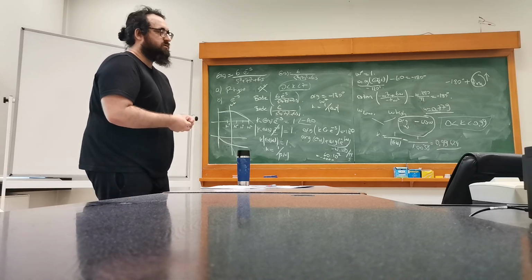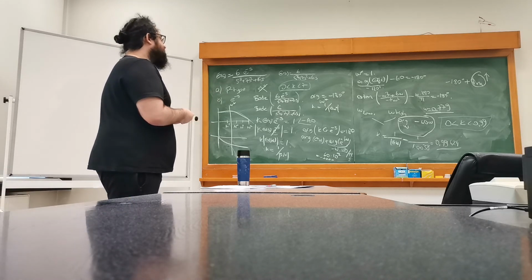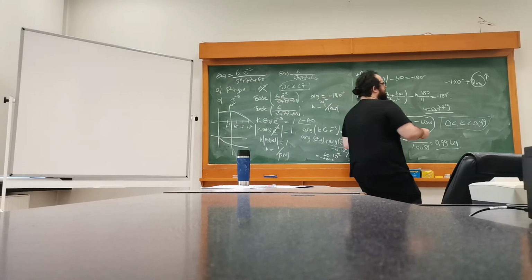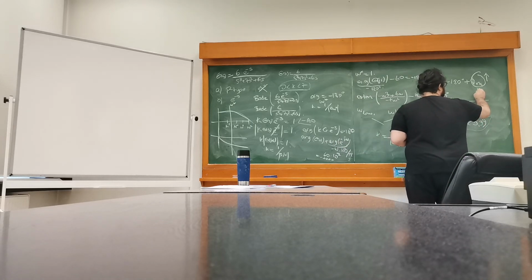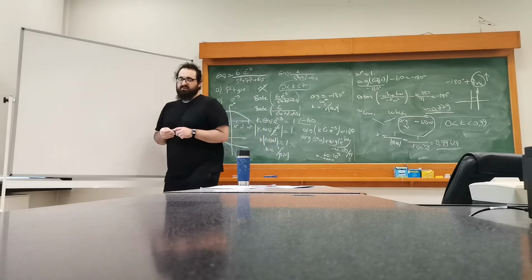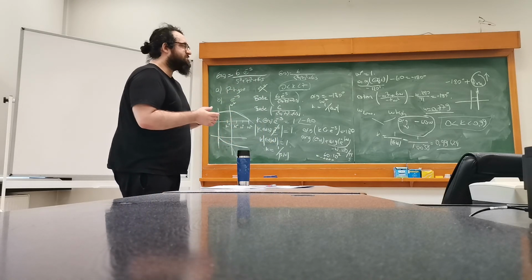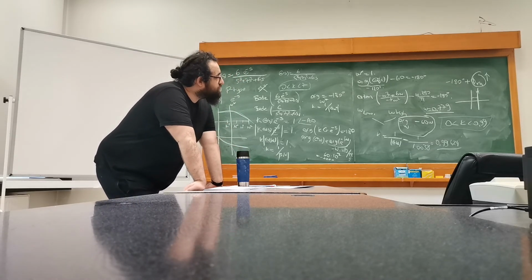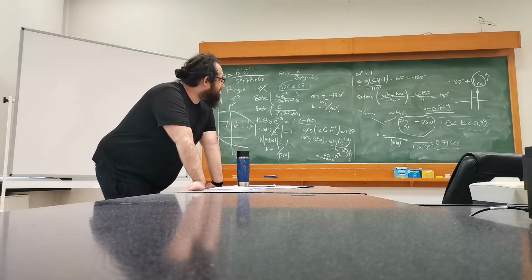If the phase margin is low, if you don't have that huge phase margin, then you're basically in trouble, because you're close to the j omega axis. If this distance is not that big, if you don't have a phase margin that's large enough, that's the stability measure actually. Of course, you have also the gain margin, which is the P-type controller itself. The higher the gain margin, the better it is. You can add more and more gain to the system until it's destabilizing. So yeah, that's basically it.